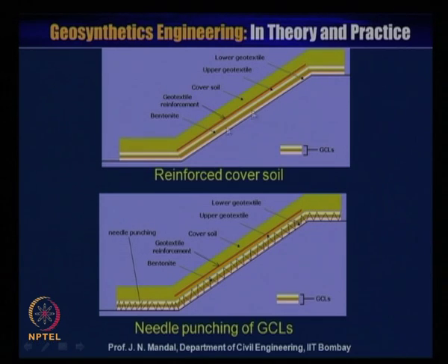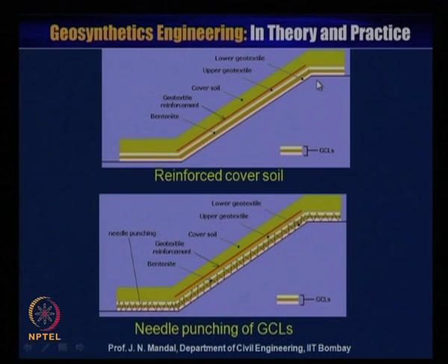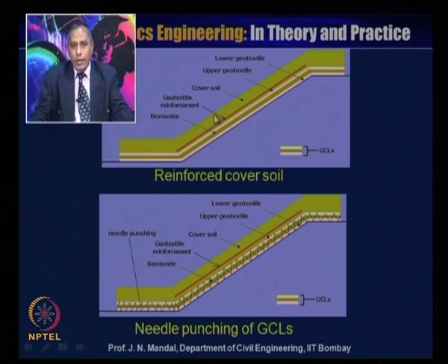Apart from the geomembrane or geosynthetic clay liner, you can provide reinforcement to make a proper slope. You can make any steeper slope or angle as you like. So you can provide sometimes the geosynthetic clay liner, also the geomembrane, also the geonet. This is all a combination of geosynthetic material.